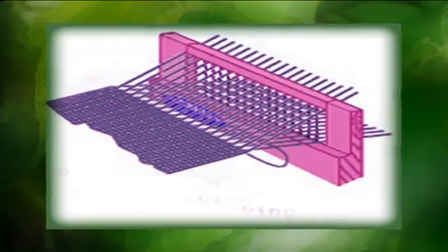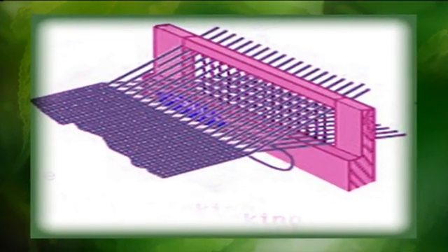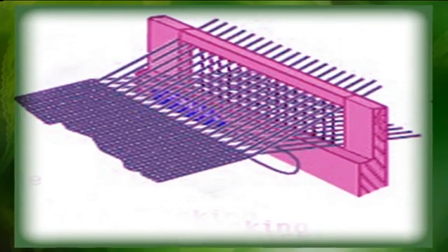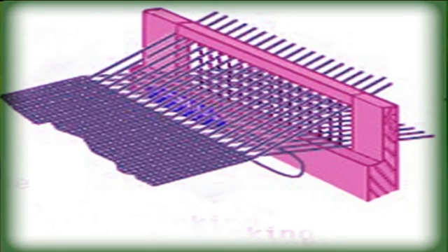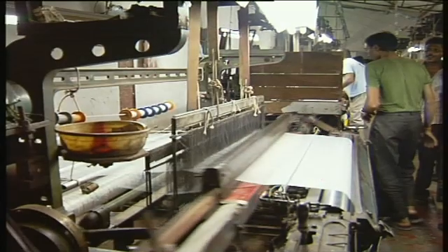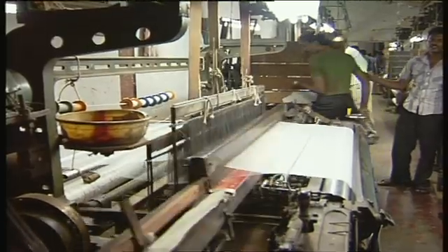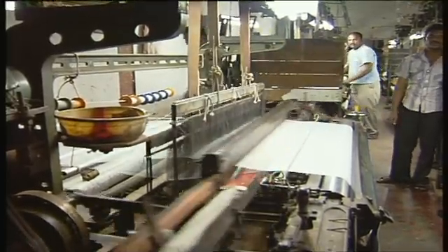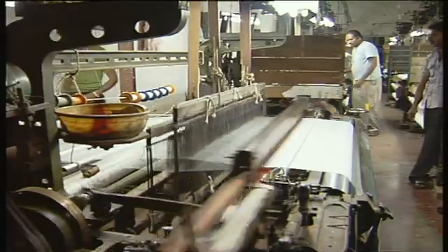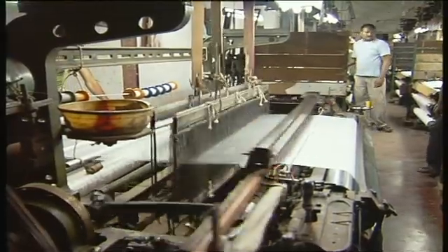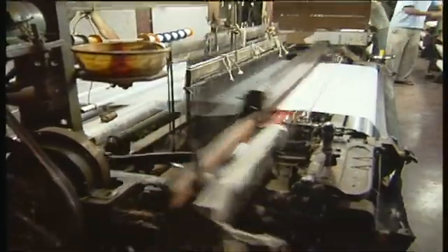A shuttle is used for picking in hand looms and also in conventional automatic looms. From the point of view of cleanness, freedom from oil stains and the avoidance of weft blocking in the woven cloth, underpick motion is preferred to overpick mechanism in the weaving of silk.